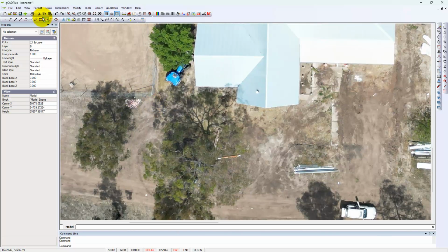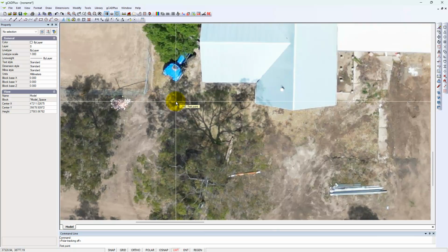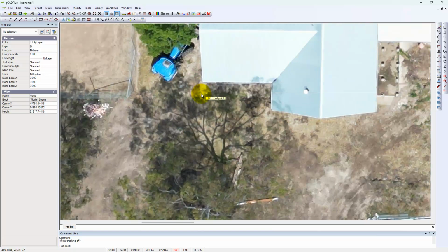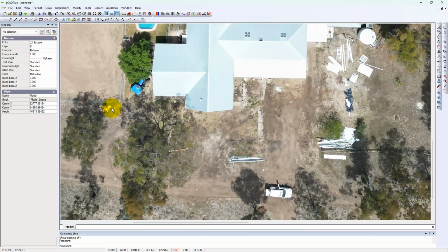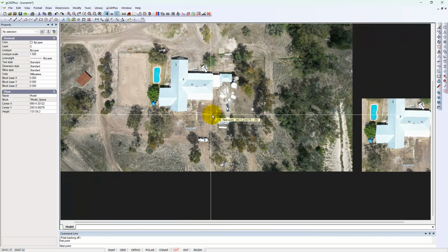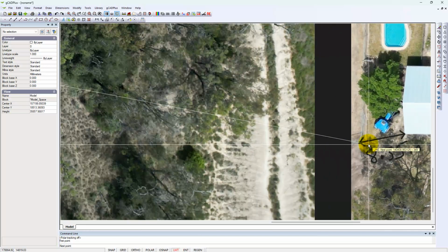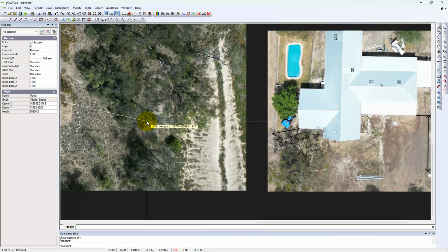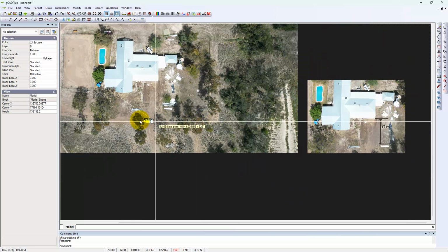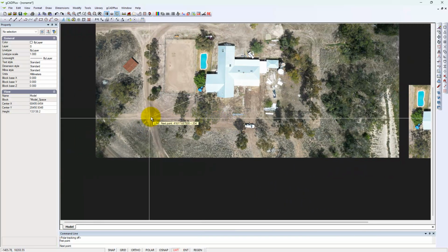So we'll just draw a line, but this time we'll come down and take polar off because we want to come at an angle. So I think it was from that corner there to, I think it's roughly the end of there, but I'm just using the wheel of the mouse to remind myself. Yeah, there's a light brown line and then a darker line, and I'm panning across.